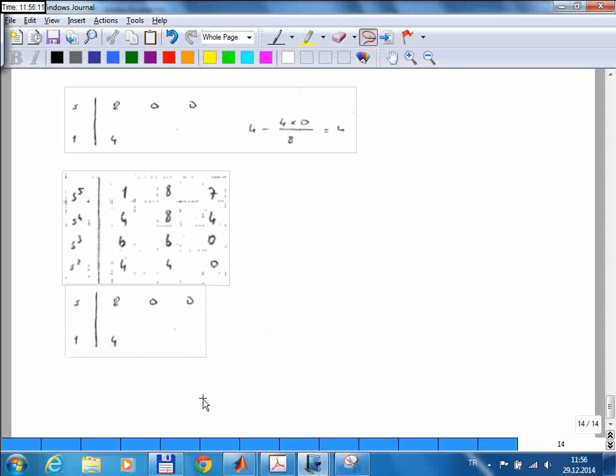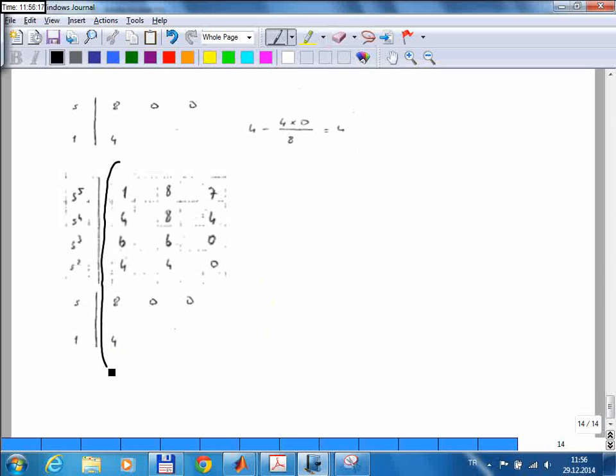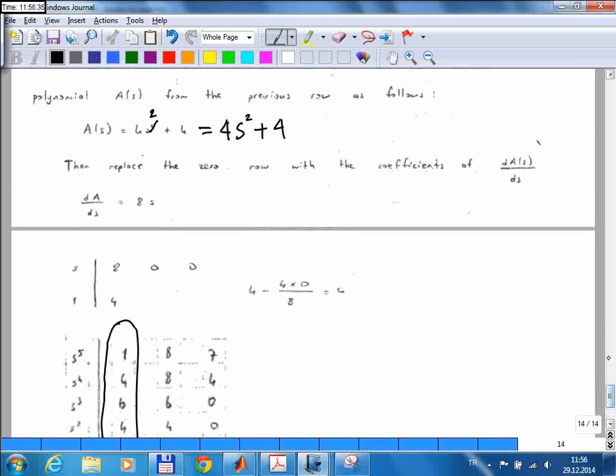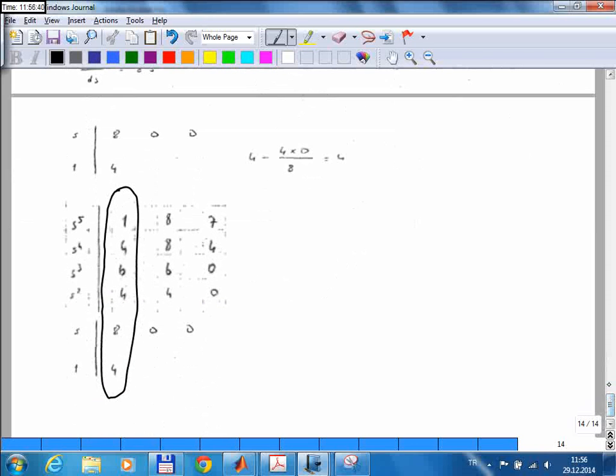Okay, so this is the array after that modification. So normally we check the first column, right? And we see that there are no sign changes after this modification. If this is what we obtained initially, then we would say that this is a stable system. But since we obtained this result after applying this modification, we cannot conclude that the system is stable.